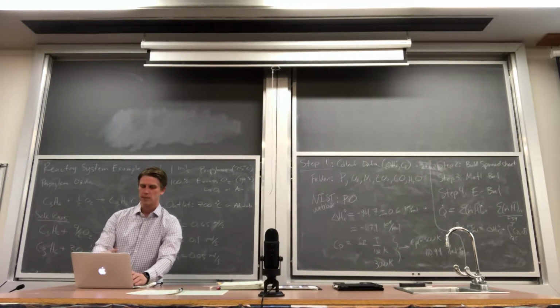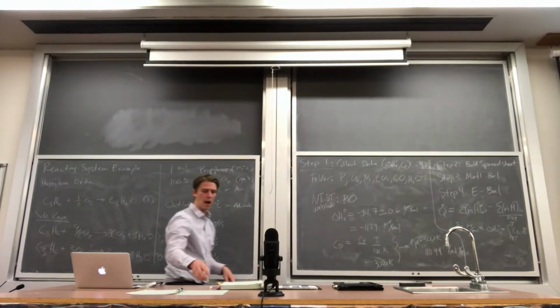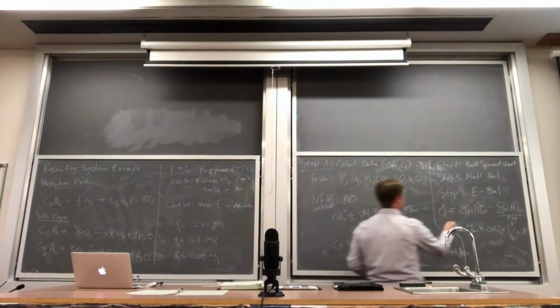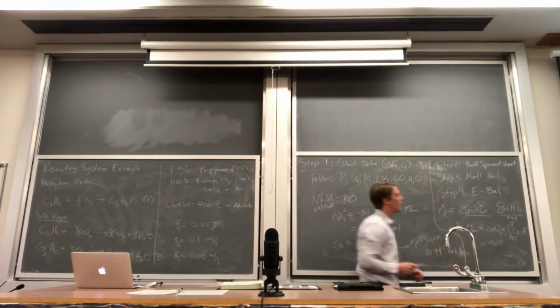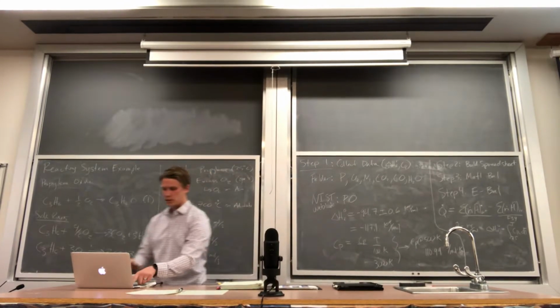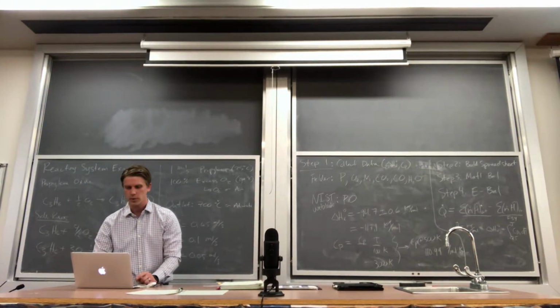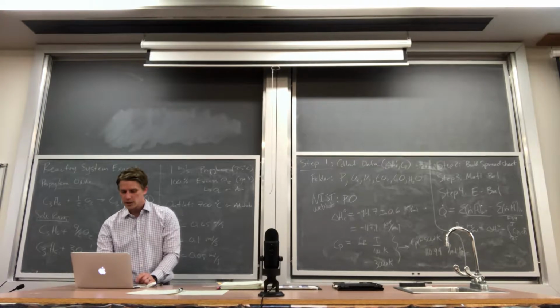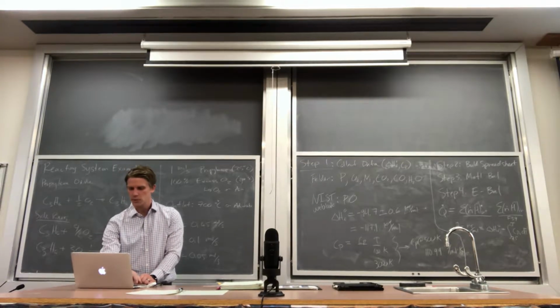And then lastly, I calculate the enthalpy out, which is this term here. I add it all up, which is this bottom one, the minus 53.2 kilojoules. I had this as kilojoules per hour. I didn't change that. It should be kilojoules per second.